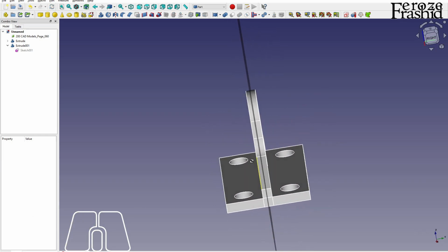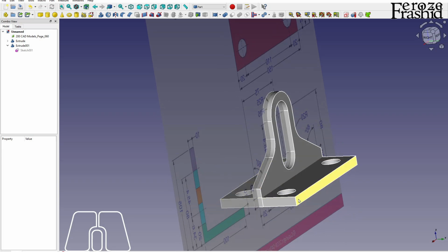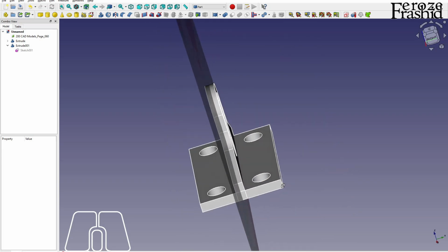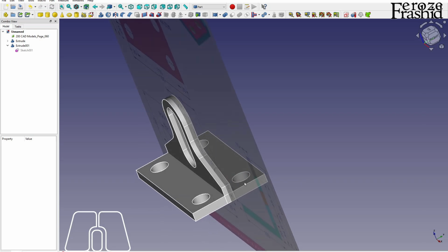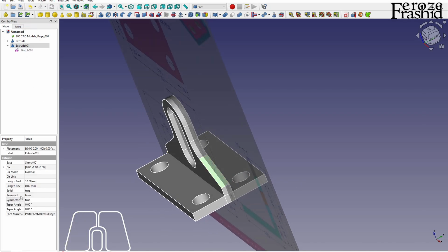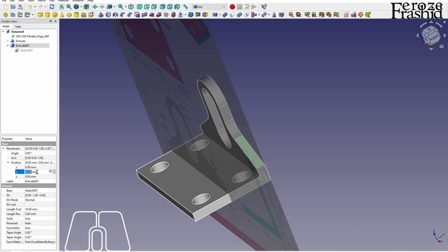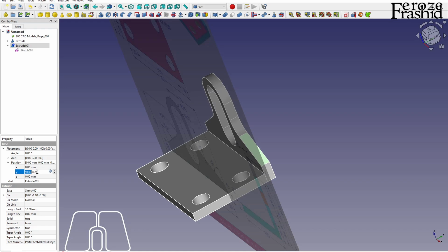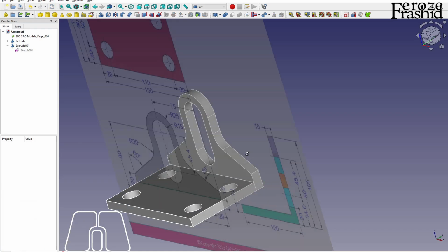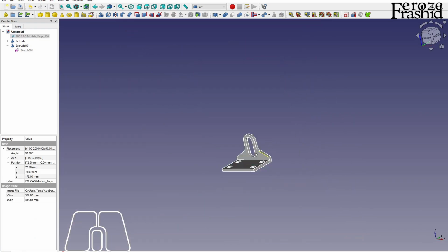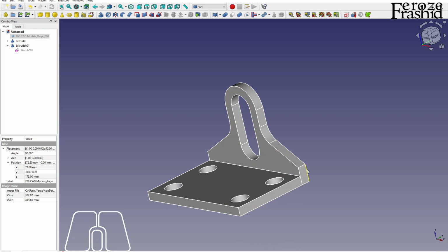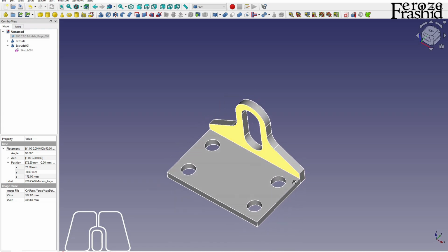All right, so as I was saying to begin with, normally we build the sketch here and then build the pad there. We don't have to if we didn't want to. I could build it here and then move it back. The sketch can be there. The part, I can move it from the placement. So this will be Y direction. See? So we go just like that and there, 50 millimeters away. That's our object, and we built it. It's kind of like building it in the factory and then moving it to the location. That's what we just did.